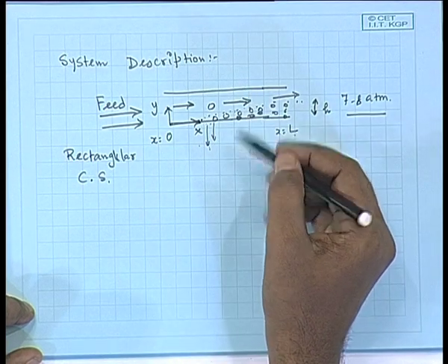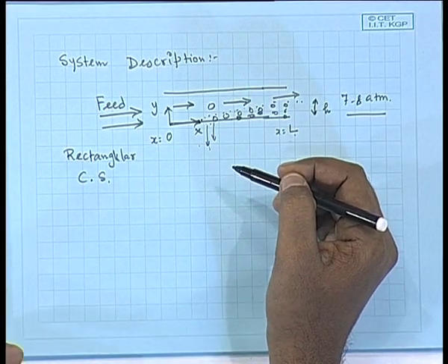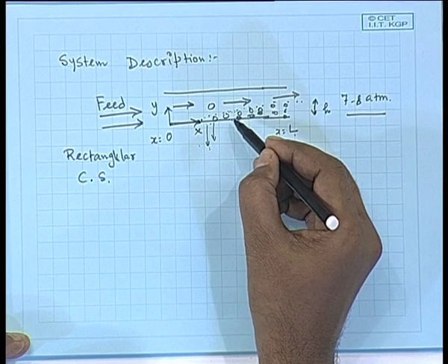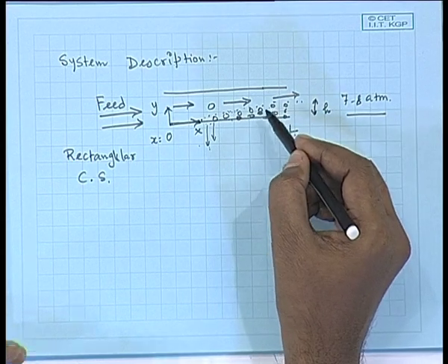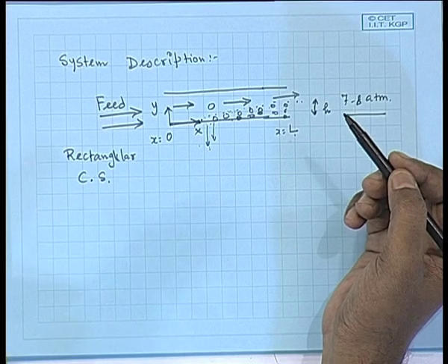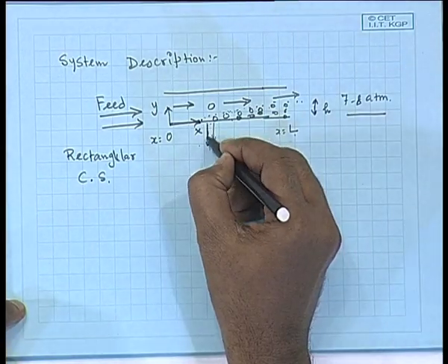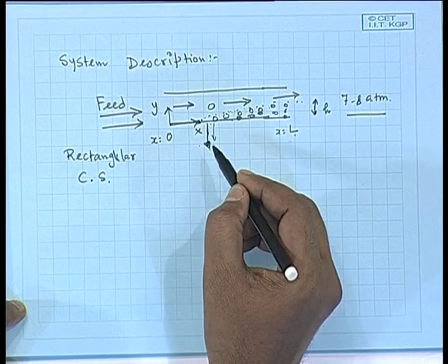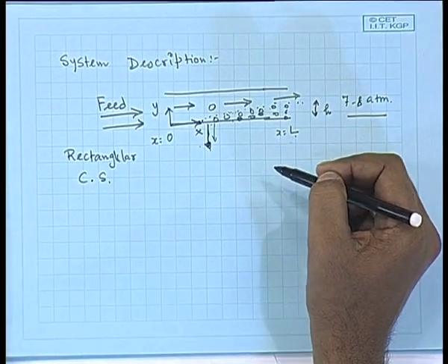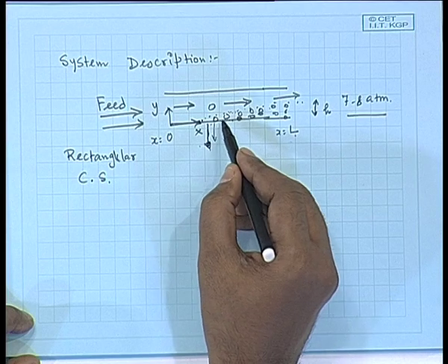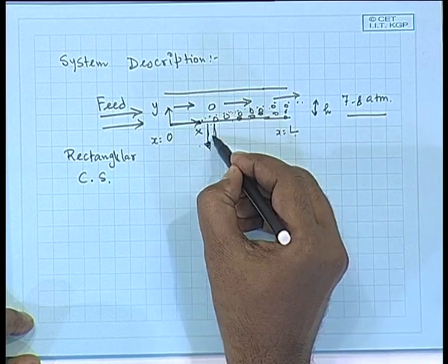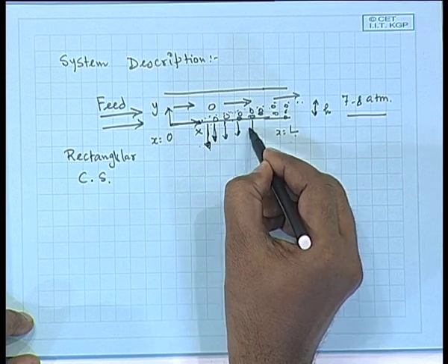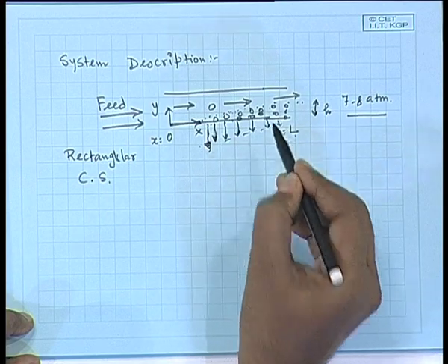Now, the solvent transport, that means the flow of water through this membrane surface, will be inversely proportional to the thickness of this concentration boundary layer. The thicker this layer, the more resistance it will offer against the solvent flow towards the membrane. So, initially, since this deposition is very small, you will get the maximum permeate flow rate. This side is called permeate, that is being permeated. As the thickness of this boundary layer increases, the flux decreases. So, continuously you are going to get a smaller permeate flow rate.